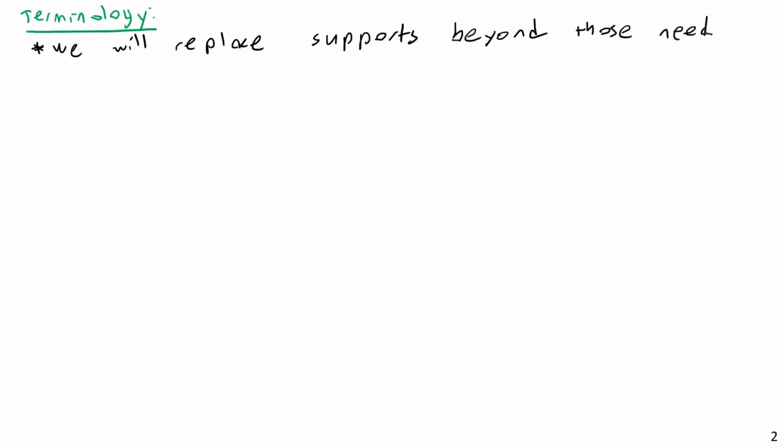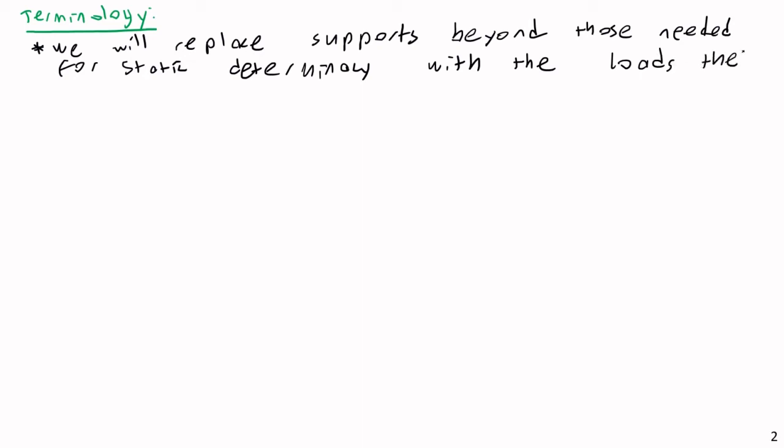Again, the big idea is that we will replace redundant supports, or supports beyond those needed for static determinacy, with the loads those supports would have through them.